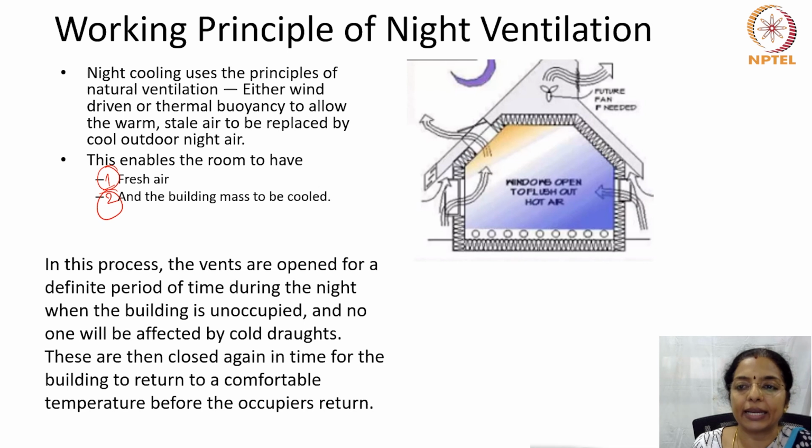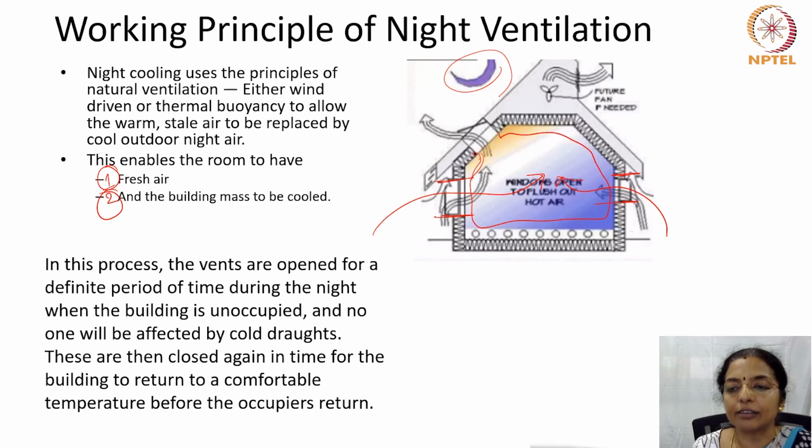So in this concept, at night, the openings are all opened up for cool air to enter the building. The cool air which enters the building lowers the temperature of the indoor air, and that is absorbed by the internal surfaces.